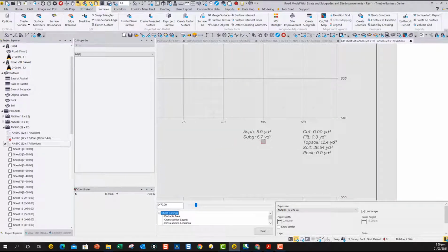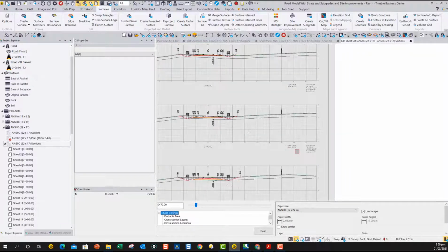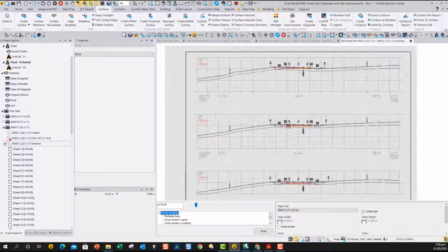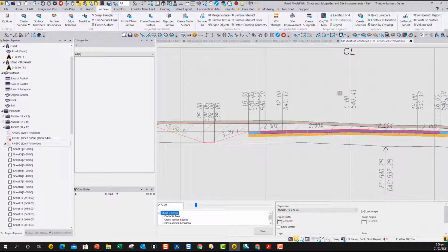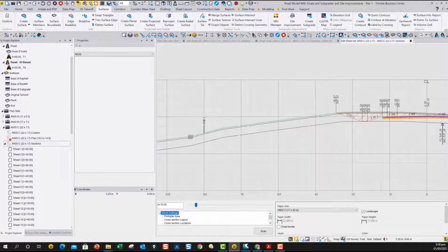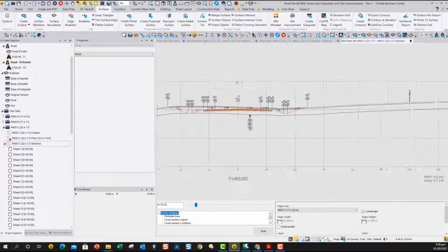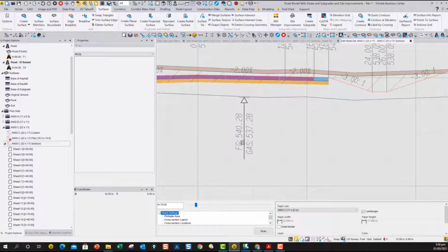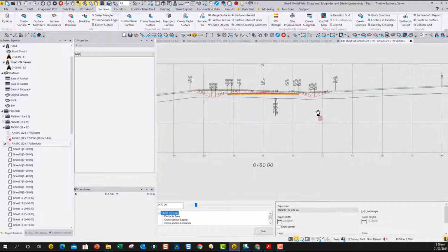Same thing over here. I didn't bother adding that over here, but I could have done and add these in. So then I'd have my volume quantities and my subgrade quantities for earthworks and subgrade here, and my area quantities over here. And then you can basically label the points and attributes across here as you see fit to get what you want. And you can see I'm picking up the right-of-way line left and right in here, as well as I'm picking up the storm line that I had, or the gas line in this case, at this elevation, at this point right here in the cross sections.